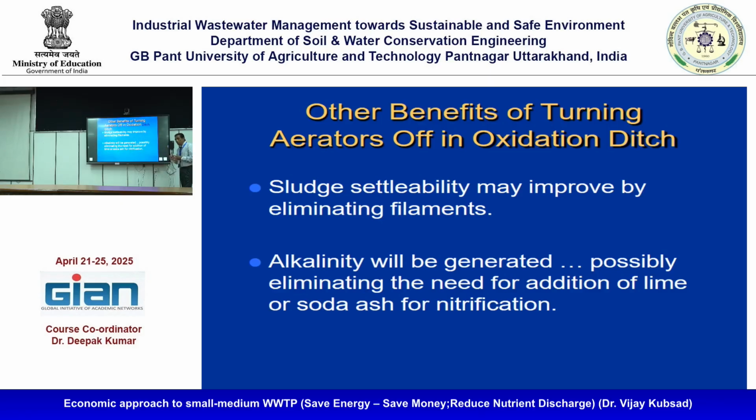But when you stop aeration, there is another consequence also. The settleability and the type of bacteria will cause a little harm. That is why we have to have a very balanced approach. It is really tough to stop it. You can keep it low, but completely stopping may cause a problem. If all the sludge settles down, it may create anaerobic conditions, and your purpose of treatment is not served. That is also there.